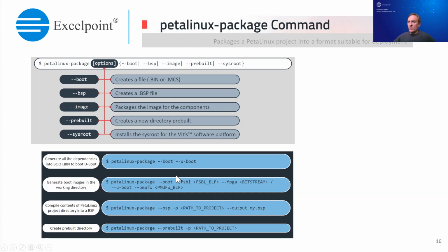Again, here are a number of examples on how to use these commands. So the first two commands generate a bootable image that can be used directly on a Zynq UltraScale+ MPSoC device. And so we'll be using some of these while we build.